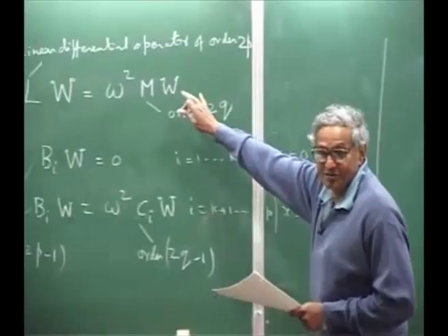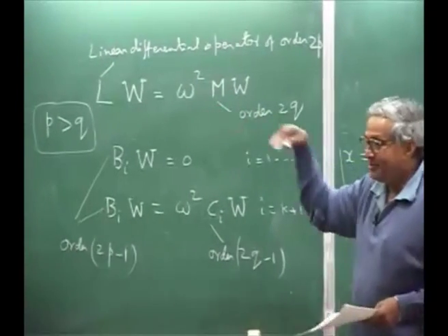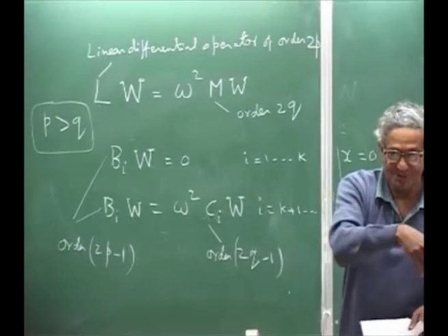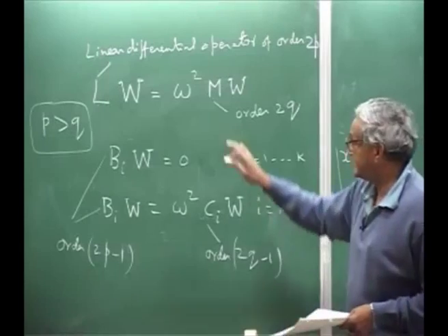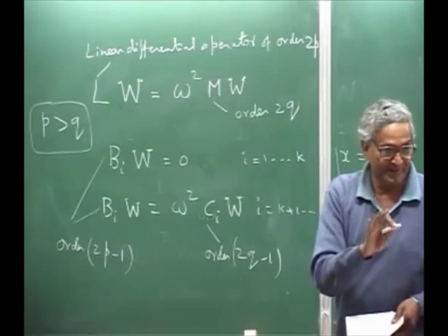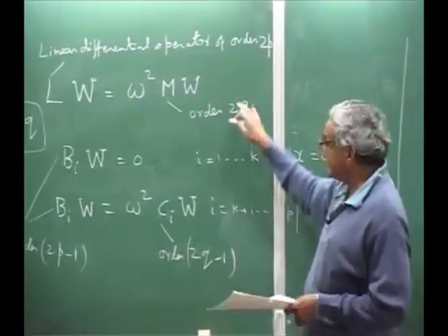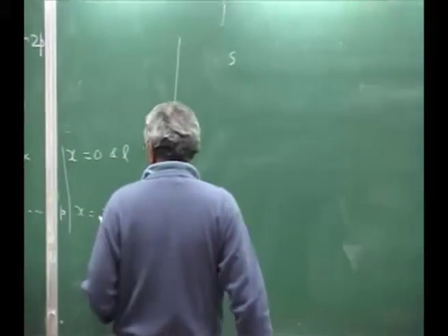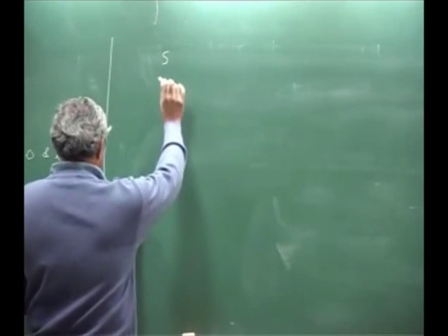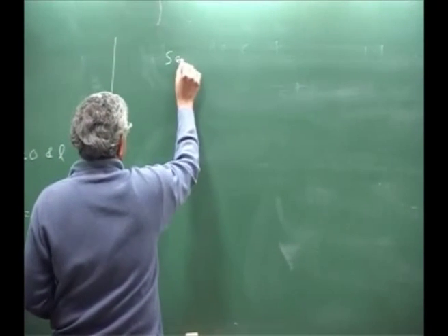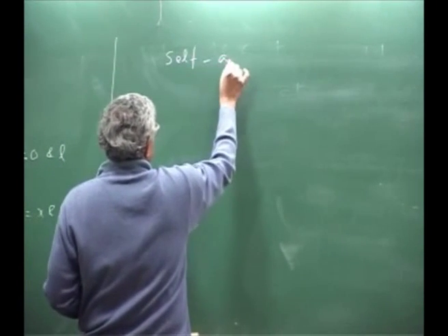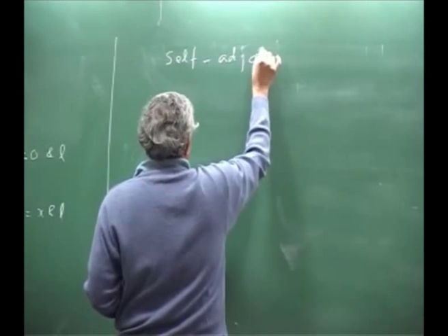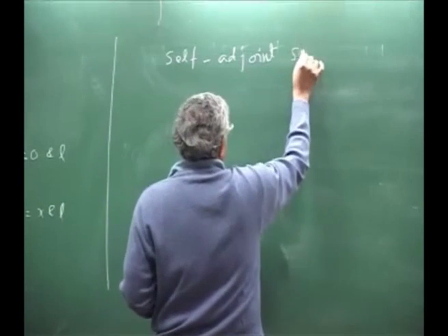Please understand, there is no damping, dissipation, nothing. Whatever work is done goes into the strain energy, and this is a free vibration problem, because we don't have any forcing function. So this is a conservative system, and self-adjoint systems.